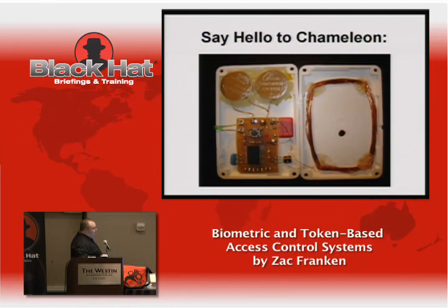There's a few other components here, but basically you pretty much need a PIC chip, a transistor, a capacitor, a resistor, and a little resonator to make the PIC chip work. That is the totality of the hardware you actually require to emulate a unique tag.